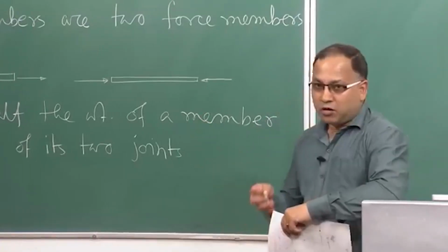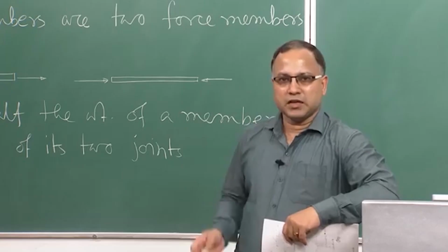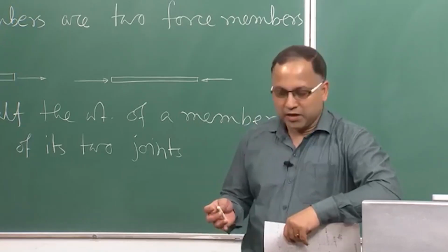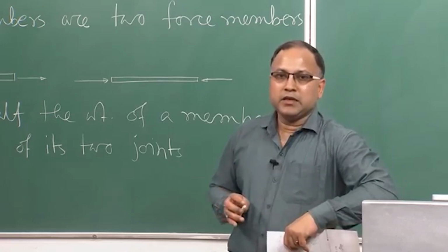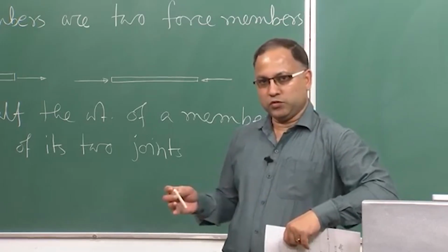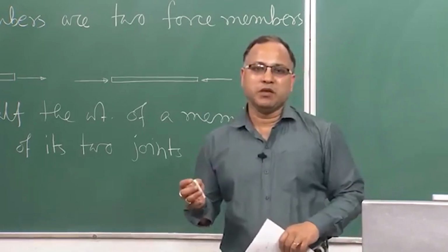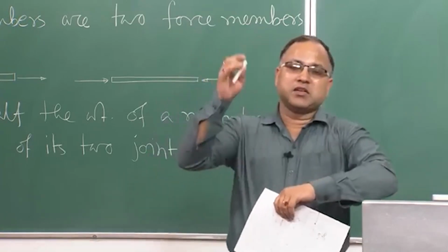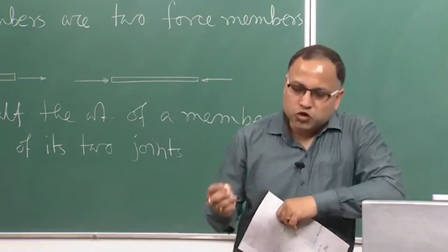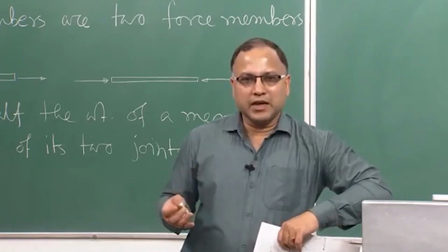Every member in the truss has some self weight. But generally the truss is designed to carry a load such that the self weight of an individual member is very negligible compared to the externally applied load. Therefore, most of the times we neglect the self weight.